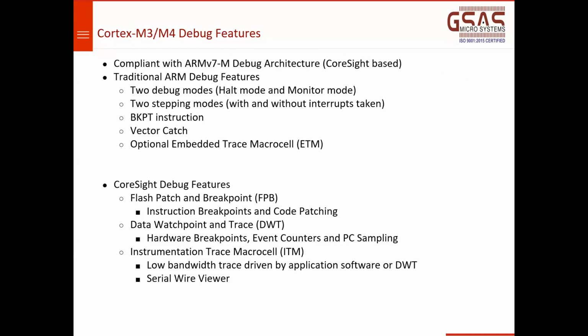But on the other hand, if you're loading code to the RAM, yes, you can set any unlimited number of breakpoints. And to see the memory location in the watch window, you have to put a breakpoint, stop the processor, and then view it. It's like stop, analyze and go. There was also an embedded trace macro cell. We'll talk about ETM later, but ETM basically helps in capturing the execution history.